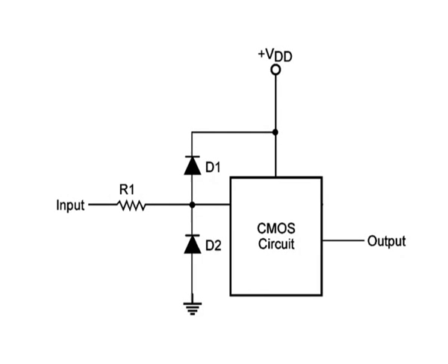The figure here shows a typical input protection circuit used in 74C, 74HC etc. series CMOS devices. A distributed PN junction is absent owing to R1 being a polysilicon resistor. Diode D1 and D2 do the same job as diode D2 and D3 as in the case of metal gate devices. Diode D2 is usually fabricated in the form of a bipolar transistor with its collector and base terminals shorted.